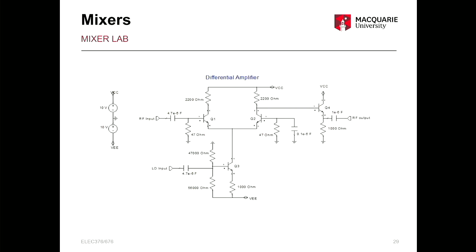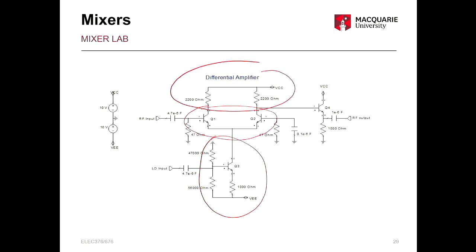So yeah, a quick look at what your circuit looks like in the mixer lab next, because some people have labs on Tuesday and won't have time to learn, so people coming after the lecture, on Thursday and Friday, have a slight advantage. I just want to make it even. So you can have a look. It's the same thing happening. You give the RF to the input, the gate, and then you have a differential pair here, and you take the output across the drain resistors.